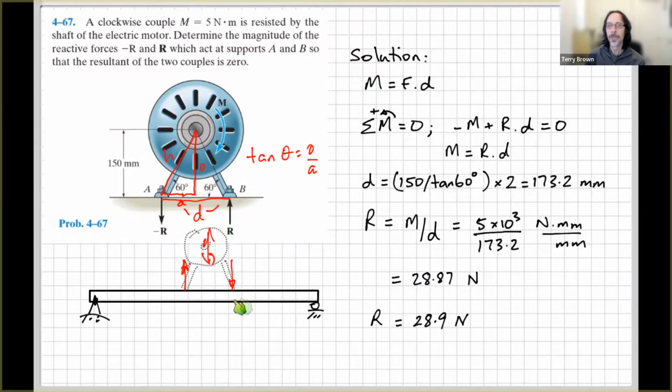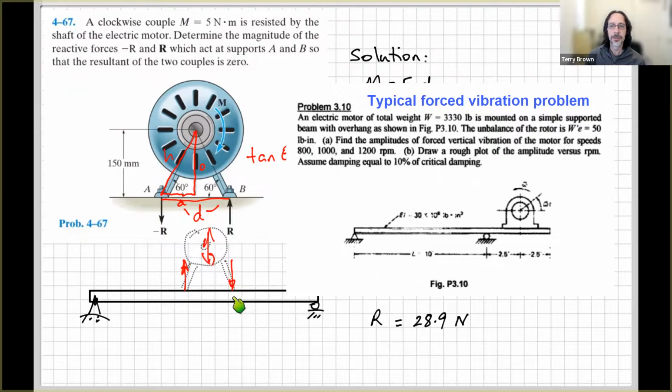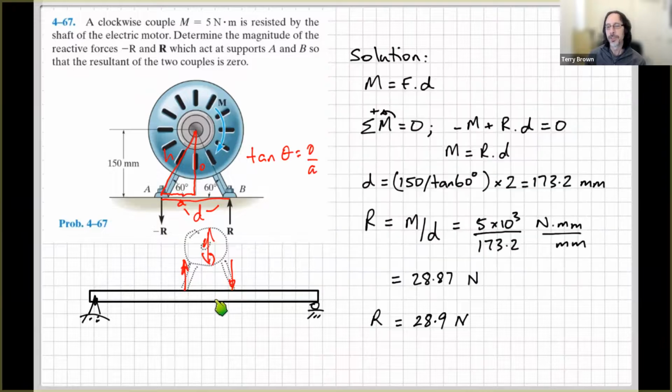Okay, and you'll do some subjects, if you're doing a mechanical engineering degree, either UTS or anywhere else, you'll need to look at calculating the natural frequencies and the mode shapes of the structures that a rotating machinery like this will be sitting on, to make sure that you don't set up a resonance in that beam. All right, so that's it for this problem.